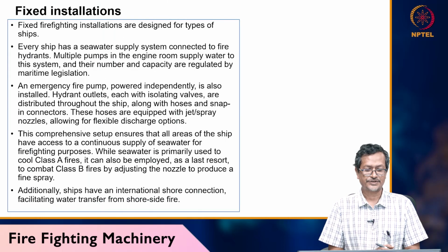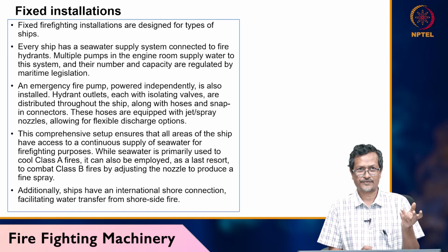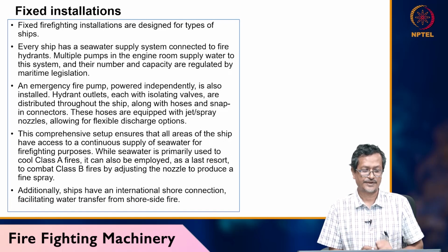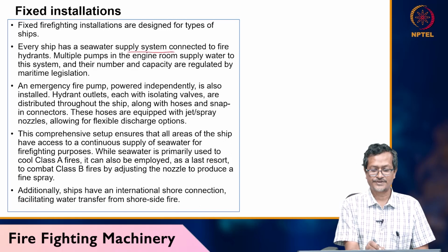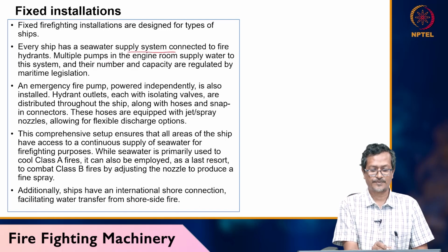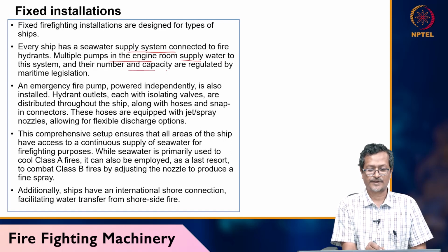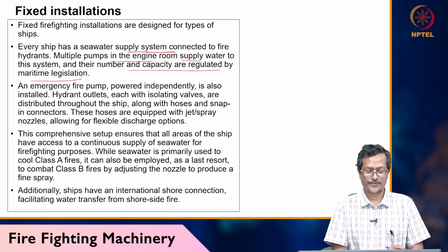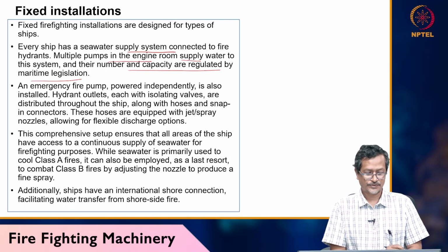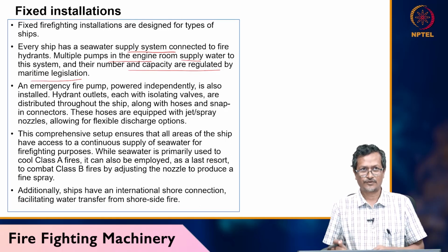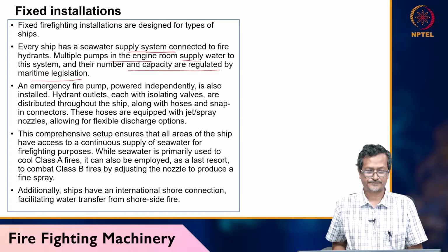So, fixed firefighting installations: there are different types of fixed firefighting installations, designed for different types of ships. Okay. Every ship has a seawater supply system connected to fire hydrants. Multiple pumps in the engine room will be supplying water to the system, and the number and capacity are regulated by maritime legislation. An emergency fire pump will also be there. Okay. So, using this you are controlling your fire on board.